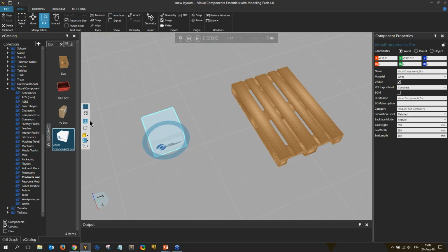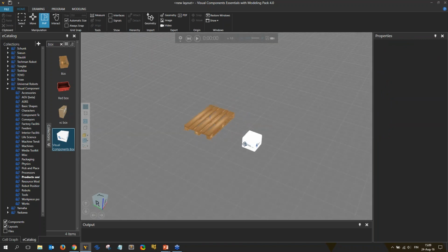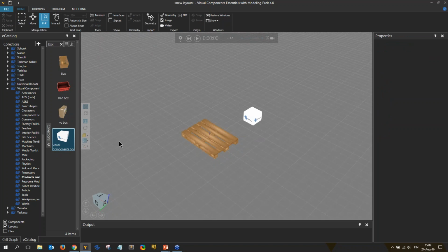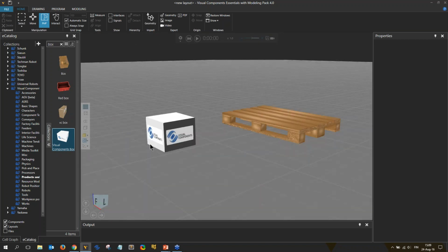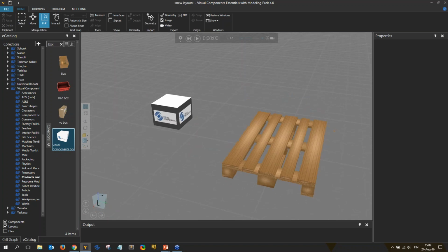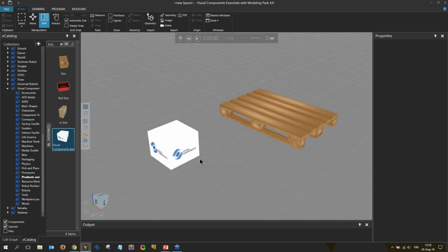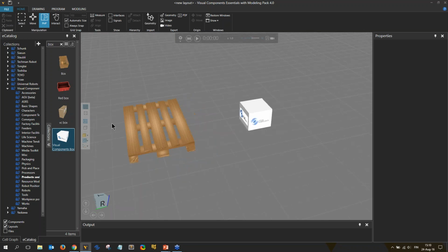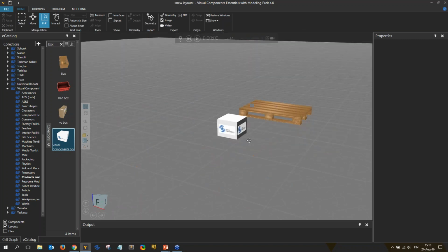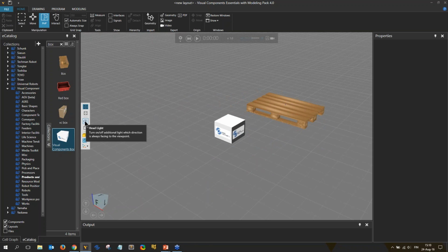The next one looks a little bit like a light icon on your car dashboard. That means a headlight. There's always a light source in 3D which makes these things visible in the layout. When the headlight is on, like in my settings, the light source follows the camera. So we're always on the bright side of the 3D model. If I disable this, you can see that the box is quite light from this side, and from this side it's pretty dark. As a normal mode, I always keep the headlight on, so I always see what I want to see. But if I want to get, for example, a little bit more artistic screenshots, sometimes it's useful to turn the headlight off, and you get a little bit more artistic feeling, or it emphasizes the shading a bit better. But go ahead and try it out with your models.